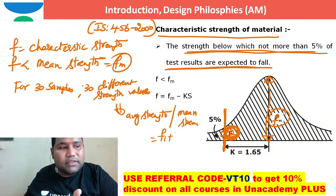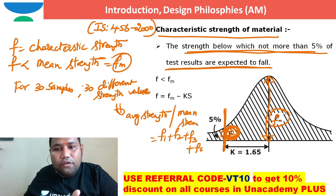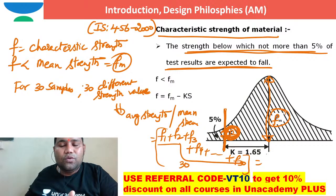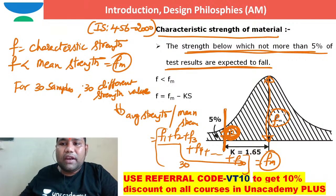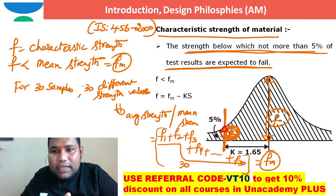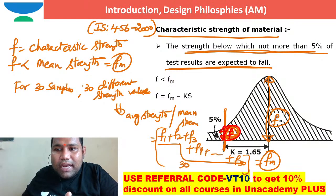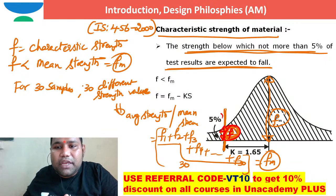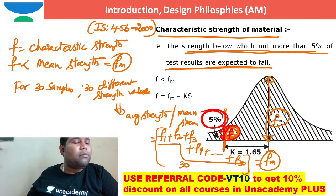How to work out the mean strength? Maybe the first specimen strength f1 plus the second, third, fourth specimen strength, up to 30 specimen strengths, divided by the number of specimens, which is 30. If I do this, I will get the mean strength. Compared to the mean strength, the characteristic strength, which is a small f, is less than the mean strength. This characteristic strength is at a probability of 5 percent.